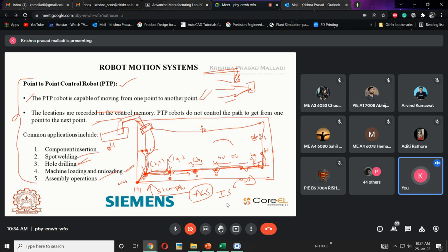Here he is giving the value 0 comma 10, and from this point he will be giving 0 comma 10, here they will be giving 0 comma 10. From this point he is giving this point as minus 40 comma 0. So it's like this. Based upon the user interface and the operator's interest, he can pick incremental or absolute in the point to point conditions.